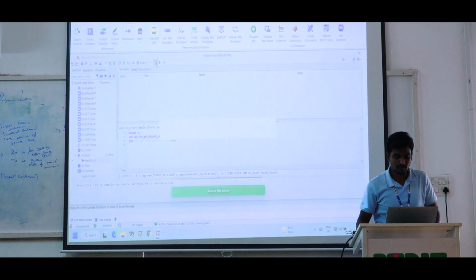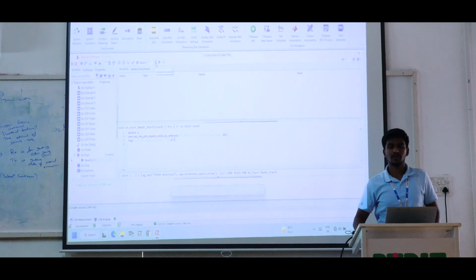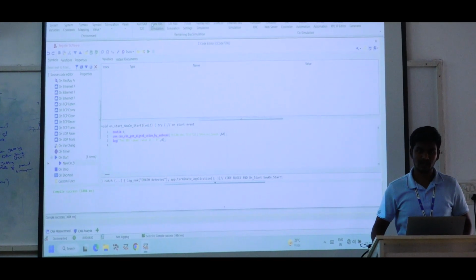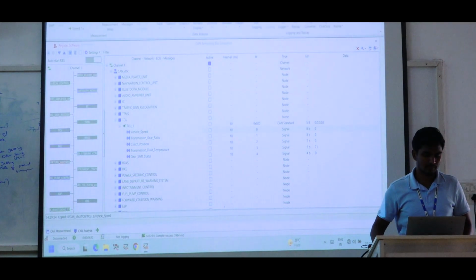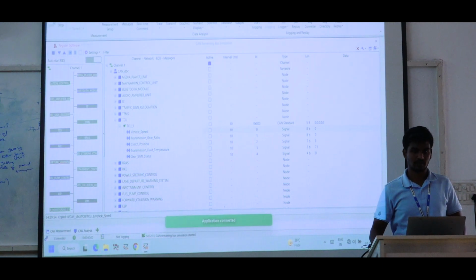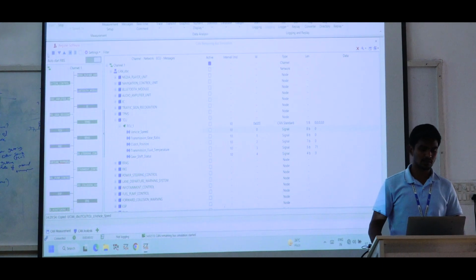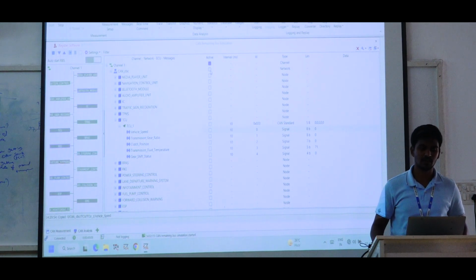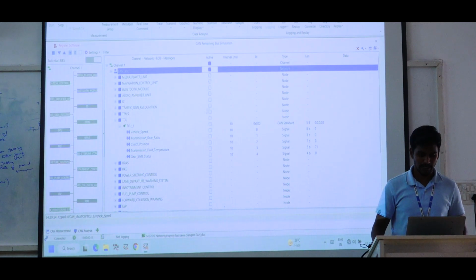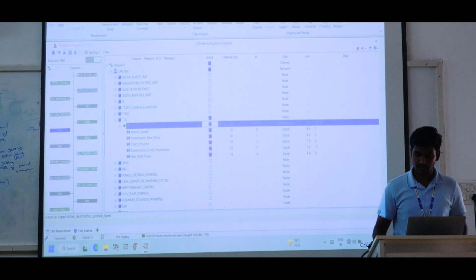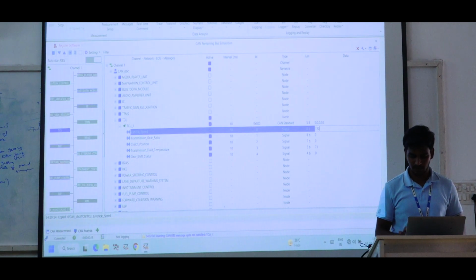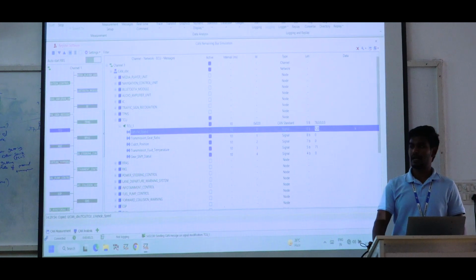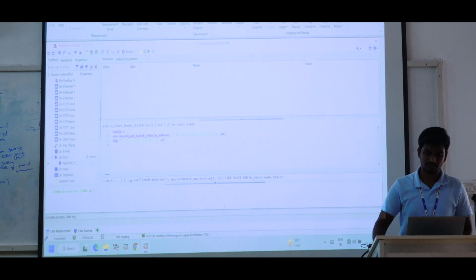Now compile this source. After compiling, don't start the scripting yet. Go to RBS, scan RBS, and turn on our main simulation. Both should be connected. Next check whether our database is active or not; if it is not active, please activate it. Activate the node and the message also. After that, give the vehicle speed as 120. You have to manually enter the data frame vehicle speed as 120. After entering this, you just start the script.